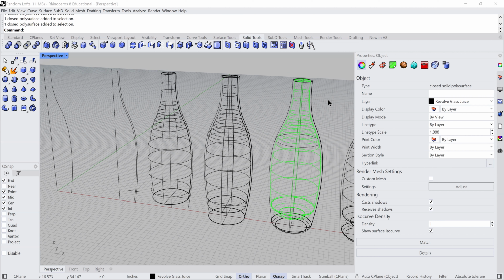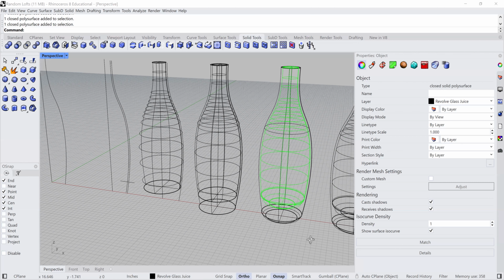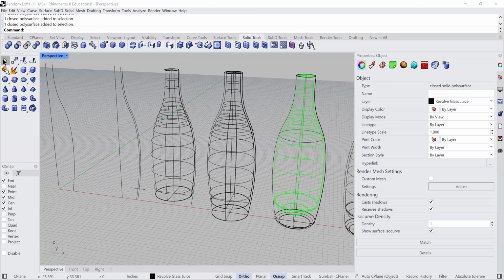So what we try to do as designers, especially creating renderings, is imitate what that might look like. I've worked with some designers who try to control that inner shape very definitively, and you really can't. We can only work with the blow molding process. That will become more apparent as I do some of these other tutorials. But for this one, I'm just going to estimate this little radius here at the bottom. So it's a curve. That's about what we could create. The glob of glass will create that thick bottom. So then we just have to come in here and radius these two shapes independently.